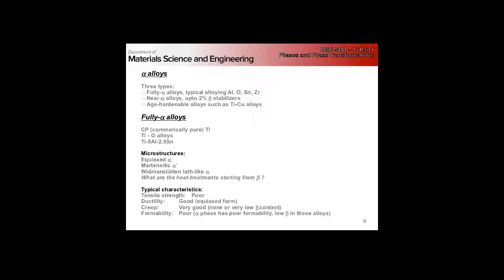How would we get an equiaxed alpha structure? If we're coming down from the transus, where does the alpha nucleate? At the grain boundaries, right? And then we talked about how they either coat the grain boundaries and then grow in like Widmanstätten plates. So how do we get an equiaxed structure? Large quench. Oh, I mean, think about the processing. How have we achieved a nice equiaxed structure in steels? So either low undercooling or thermomechanical processing.